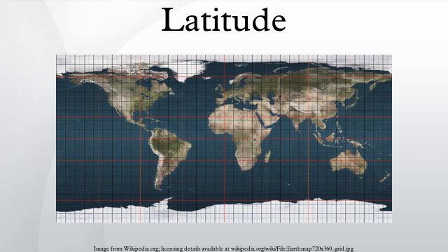The conformal latitude defines a transformation from the ellipsoid to a sphere of arbitrary radius such that the angle of intersection between any two lines on the ellipsoid is the same as the corresponding angle on the sphere. A further conformal transformation from the sphere to the plane gives a conformal double projection from the ellipsoid to the plane. This is not the only way of generating such a conformal projection. For example, the exact version of the transverse Mercator projection on the ellipsoid is not a double projection.